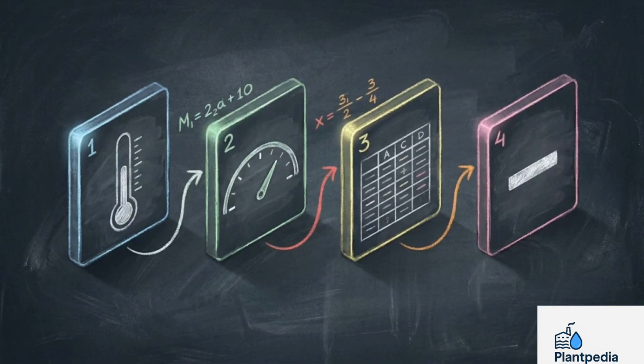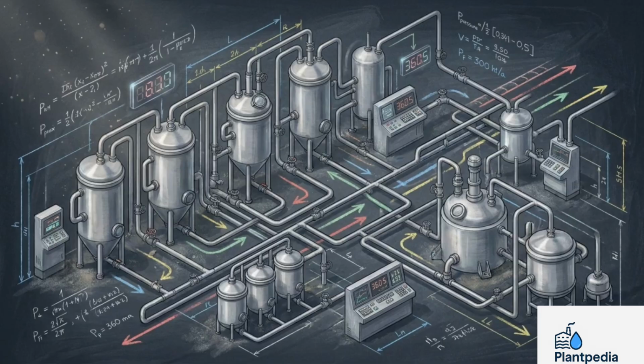By pulling live temperatures, checking your vapor pressure, referencing your steam table, and doing the math, you convert raw gauge data into actionable intelligence, keeping your ZLD system safe and efficient.